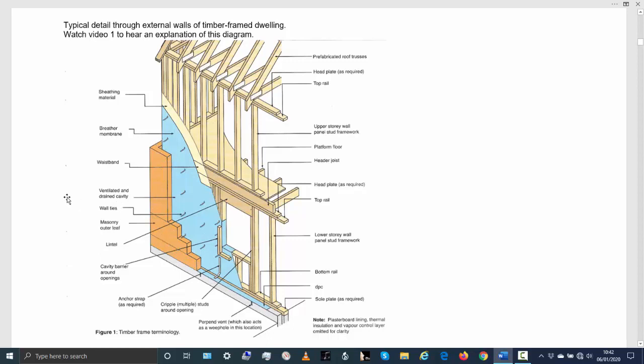Again, the masonry here is shown in brickwork, but in your property it's actually not brickwork, it is masonry, and that masonry leaf is tied to the internal leaf. Those leaves are tied together. You can see the two, they're not completely independent. They do work together, and they do work together to resist the wind loads, sideways wind loads.